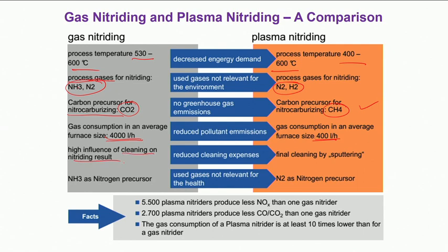Cleaning prior to the treatment is very important, because in any of these high temperature processes of iron based components, why only iron, let's say titanium or chromium or all these metals are very prone to formation of a very thin oxide layer onto the surface. In case of iron, this is actually a very major tendency. So when these oxides form, they act as a barrier for any ingress of gaseous atoms from the atmosphere. So we don't want that impediment.